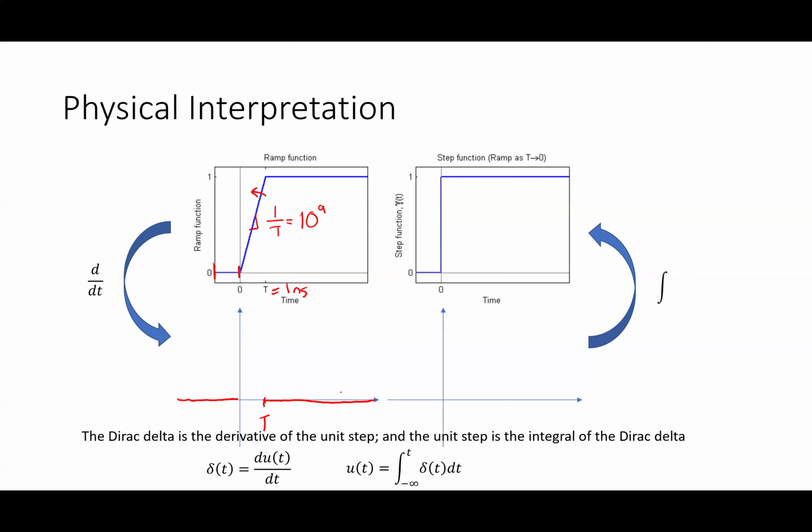Now, between 0 and 1 nanosecond, what's the slope? What's the derivative? The derivative is the slope of that line. How would I express that from 0 to t? How would you sketch that? 1 over t. 1 over t, yeah, it's a constant, right? And this guy would look like this. So he'd be really high, and then he'd go back to 0 again. Okay? So this height here would be 1 over t, which if this was 1 nanosecond,